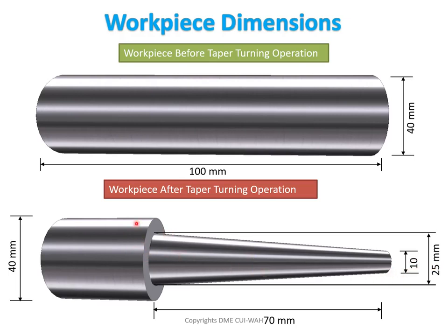So there is a step of 40 mm and 25 mm. As in the previous lecture of step turning, we have discussed step turning in detail. Here is the same. This is a step of 25 mm to 40 mm. Here diameter is 25 mm and the next part diameter is 40 mm, and the end part the diameter is continuously decreasing uniformly from 25 mm to 10 mm up to length of 70 mm. So how we will do this? We will write a code for this process in the coming slides.